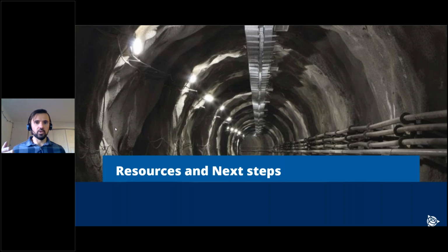You can change the interval in Trimble Access or TBC on how often you want that to be. So it's 1 meter, half a meter, or wherever. You can also, while you're in the field, define what station you want to measure. So if it's a really specific one down to the centimeter, millimeter, you can define that while you're in the field.